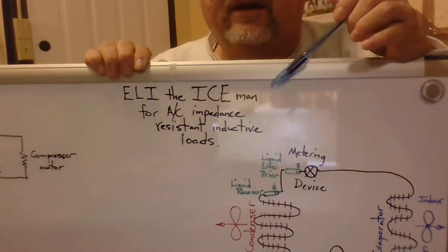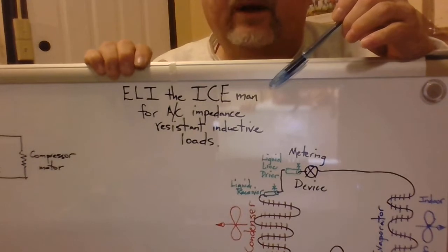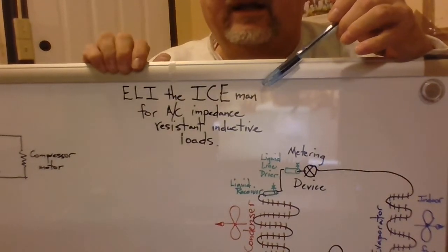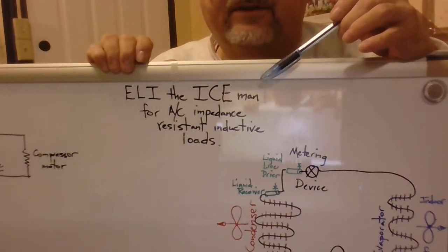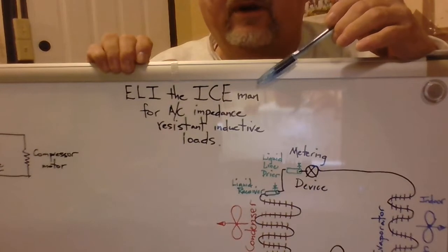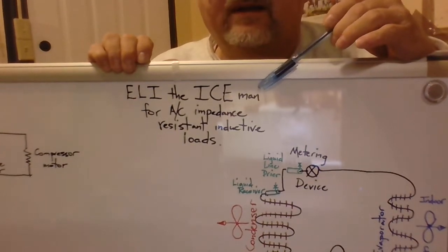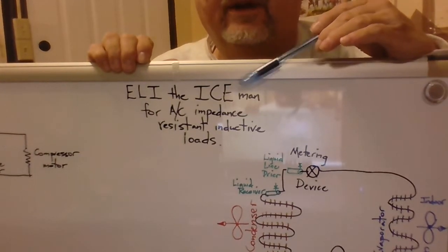So too does the current become less if you have a very incomplete electrical circuit somewhere, like under a contactor. You cannot draw enough current to make the load perform properly, and as a result you may start pulling excessive current through the other legs.